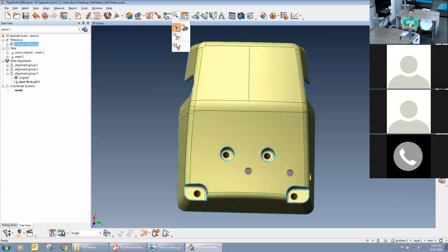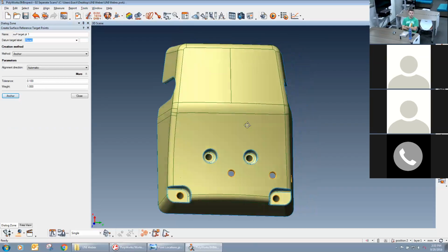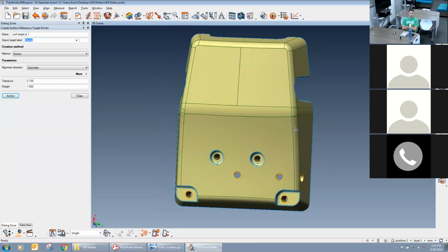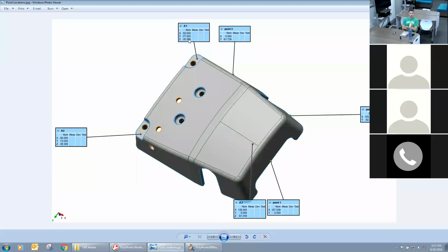So ultimately, this is to simulate either an inspection fixture or a machine points for the casting to be set on specific tooling locations before machining. So you kind of want to simulate the same type that are there. For this first example, I'm just going to eyeball the locations in. I don't have a drawing for this, so these would be my absolute numbers for where A1, A2, A3 are, and then my 3 side points or pins would be in those locations.